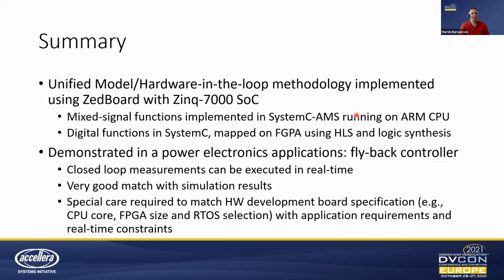That brings me to the summary and conclusions of our talk. We were able to successfully demonstrate the model and hardware in the loop approach using a rather cost-effective Z board with the Zynq 7000 processor, where we use the processor to run the mixed signal capabilities, and we use the FPGA for the digital functions. The power electronics application, our flyback controller, showed that we can do this type of closed loop measurements in real time. We had a very good match between measurement and simulation results.